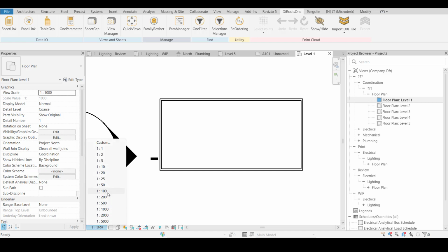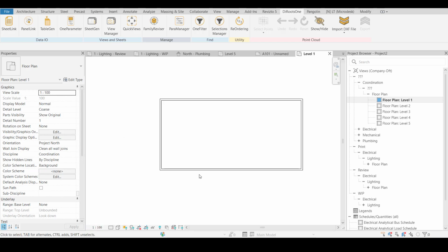When you do fit to paper printing, it compromises the scale and prints whichever way it can fit on the sheet. So that's why we don't have to do it at all. What we have to do is always print in scale, so that the precise information goes to the site. So that's our target now.